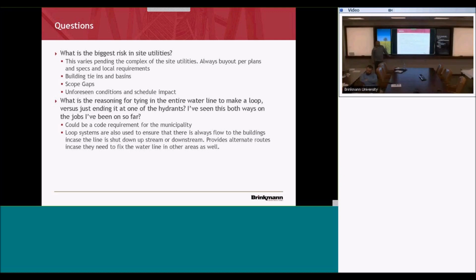Make sure, to go along with that too, if they are boring, at the end of those bores, your pipe sticks up at the end of the ground. So make sure when they go to make a connection at any turn that they're pushing those back down to the elevation they're supposed to be at and not making that connection up closer to the surface. We had an issue in Denver with that. Yeah, they should dig a hole and bore into the hole instead.